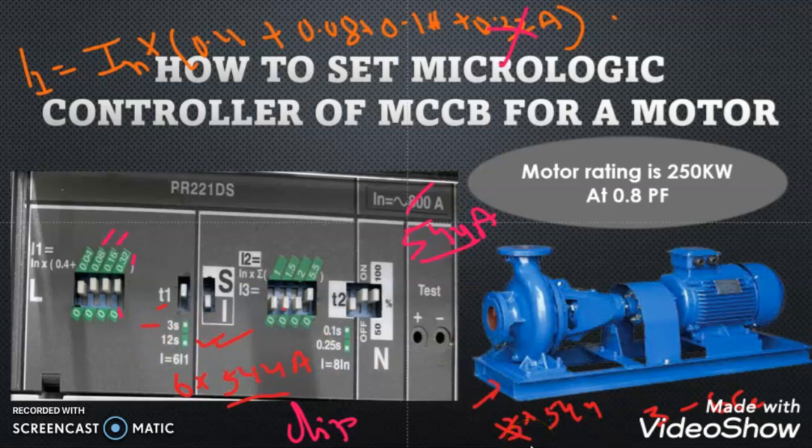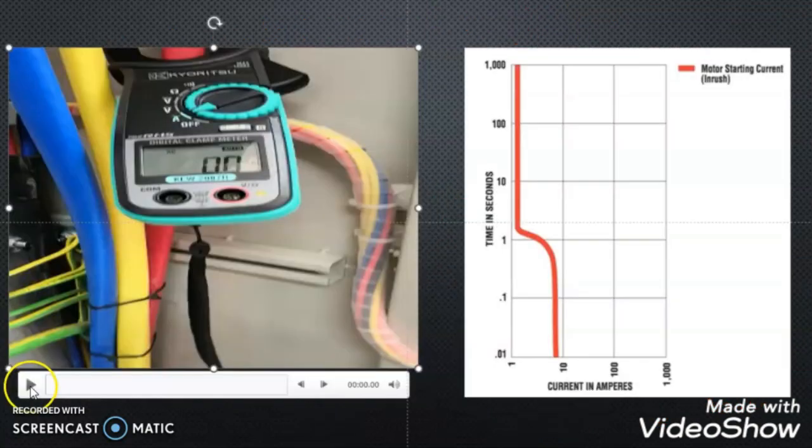Though there is a high current, 3 times the full load current, at the time of starting of the motor, the breaker will not trip because of this T1 setting. By adjusting this T1 setting, the breaker will hold off tripping for 3 seconds or 12 seconds as per our adjustment, and by that time the motor starting current vanishes and it is taking only the full load current. So with this setting we avoided undesirable tripping of the circuit breaker.